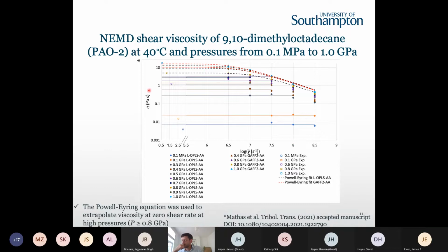Overall, there is good agreement with the experiment. At low pressures the lines are in a Newtonian regime, and viscosity was calculated by the average, while at the higher pressures we have a shear thinning region, and we extrapolated to zero shear rate by using a Carreau model to acquire the zero shear viscosity.